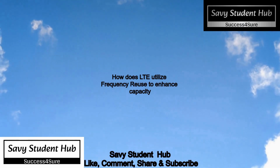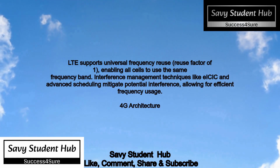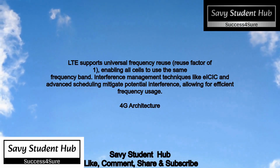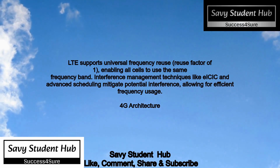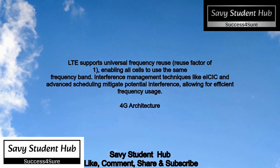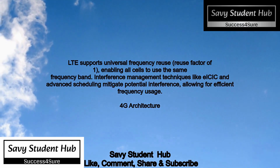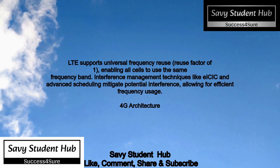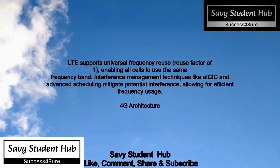LTE supports universal frequency reuse factor of 1, enabling all cells to use the same frequency band. Interference management techniques like eICIC and advanced scheduling mitigate potential interference, allowing for efficient frequency usage.